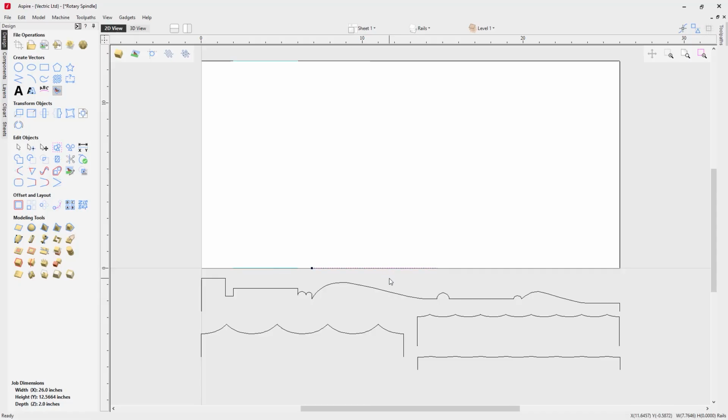Now, as before, what we're going to do is create a copy of this on the other side. So again, we'll do Control Shift and the letter V, and it creates another copy on the top side here. And what we're going to do now is ensure that the way this works is that the smaller octagonal shape comes in here at the low point and then blends into the larger height, at which point that will blend into the rest of the shape where it's no longer octagonal. So how do we achieve that?